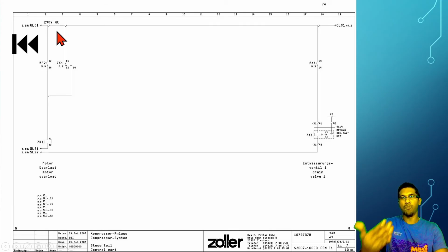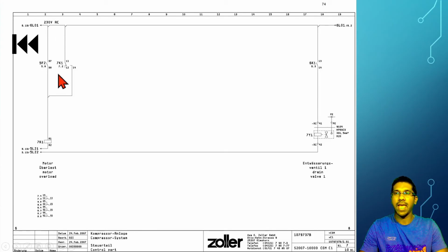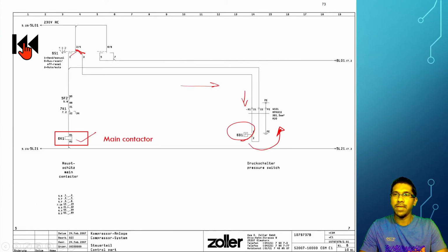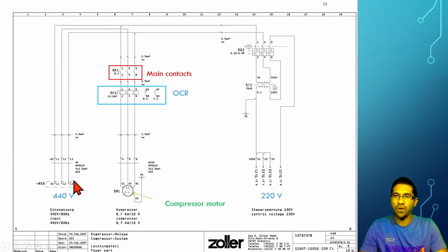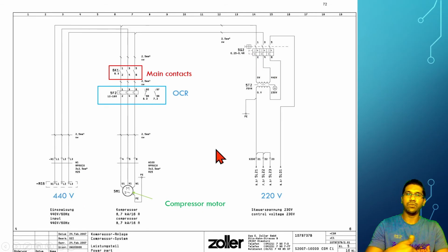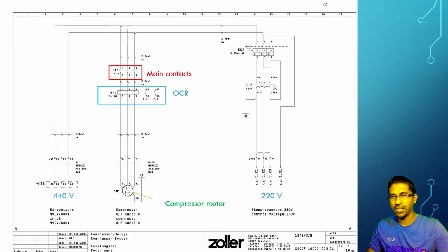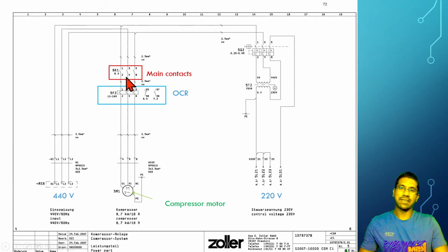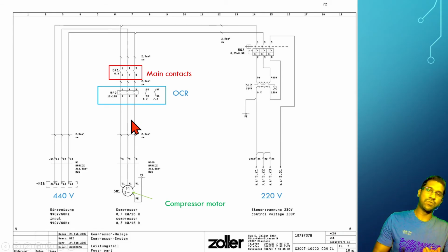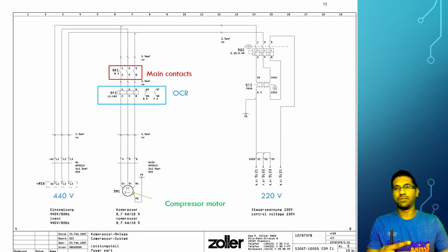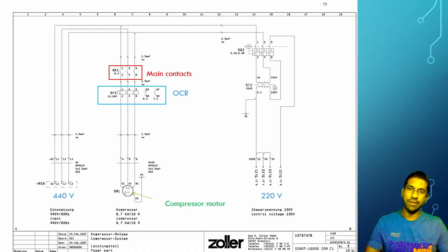That means you have to go personally to the local location and switch off the main breaker. You have to switch off the main supply. Then only you can restart the compressor, because we don't know why it is overloaded. So this is the basic. Now I just wanted to show you which page you have to refer to and how you can go back and forth between drawings.